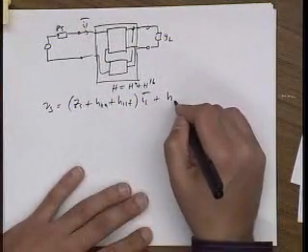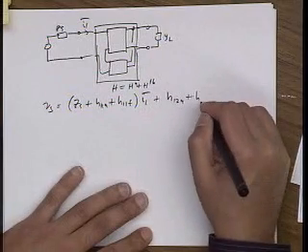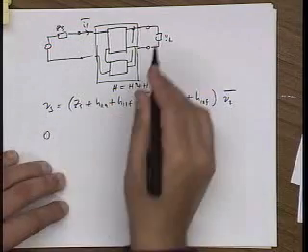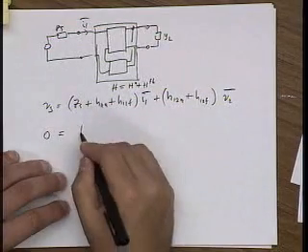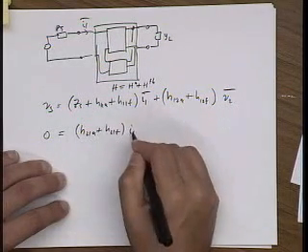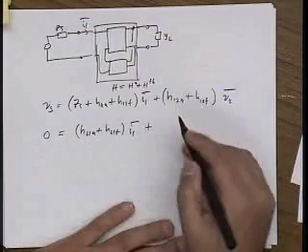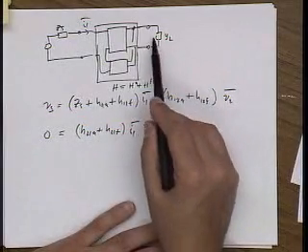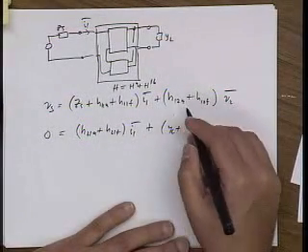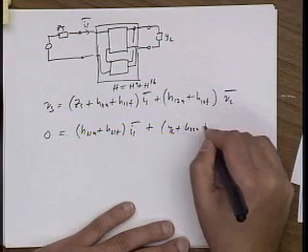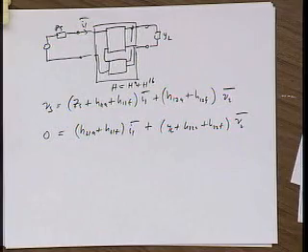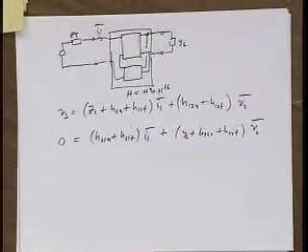So here I just have H12, which is the sum of the H12s. The output, I don't have a source, so I just have H21 of the amplifier plus H21 of the feedback network times I1. And then for H22, you can see that YL just directly adds to the H22 of the amplifier. So I have YL plus H22 amplifier plus H22 feedback, V2. Okay. Didn't do anything special.